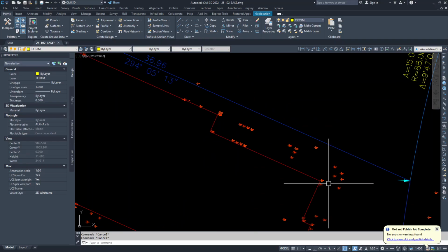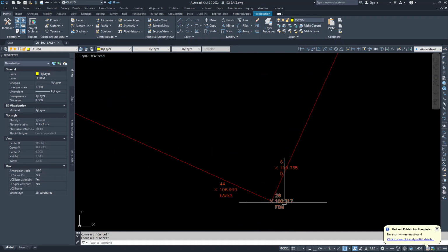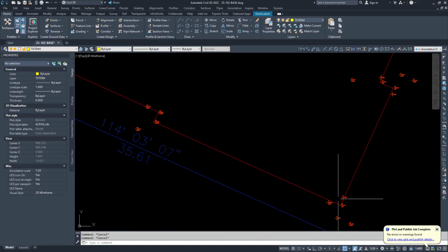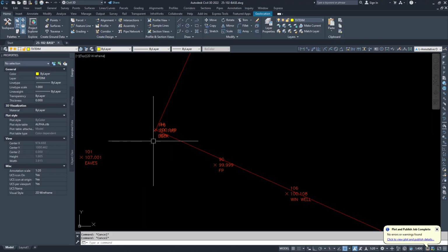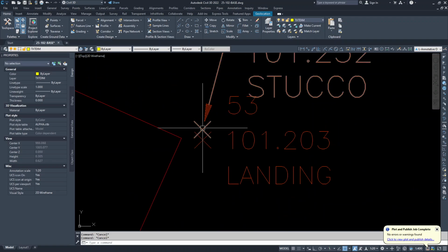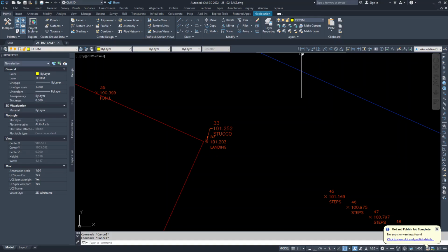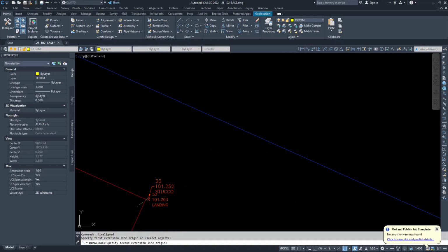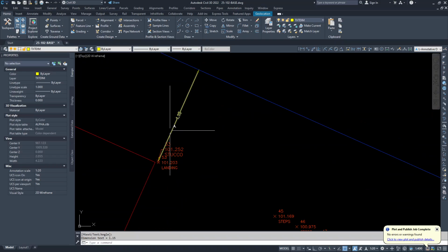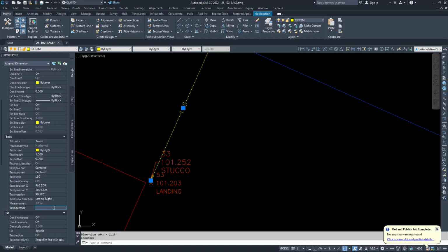So I try to keep the lines 90 degrees to each other. That's one thing. I try and find a spot where we've got 2 foundation shots that are far away from each other. Or I simply just leave it the way I have. And when I go to dimension this from the building to the property line, I just add 2 centimeters. So right now, if I do this dimension right here, I get 1.15. I go here and override it and add 2 centimeters to it. Make it 1.17.